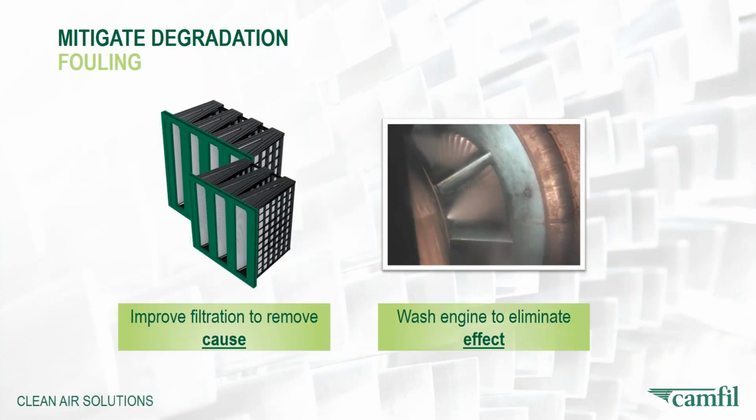So there are 2 ways to mitigate fouling. One is to deal with the effect, which I suspect most of the audience already does, and that is to do a water wash of the compressor section, whether you do it on an online basis or an offline basis, or you deal with the cause, and that is to improve the filtration to mitigate or minimize the amount of small particulate being ingested.